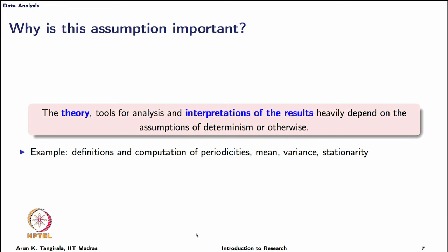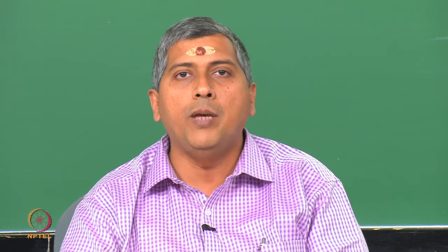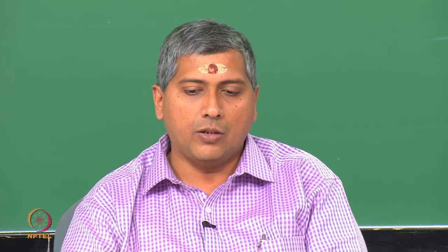Likewise, when I am referring to the average of a stochastic signal, normally a misconception is that the sample mean, which is the mean that is computed from observations, is considered as the mean of the process itself. That is not true at all. The sample mean is only an estimate of the true mean, which is defined in a different way, and we will quickly talk about it.